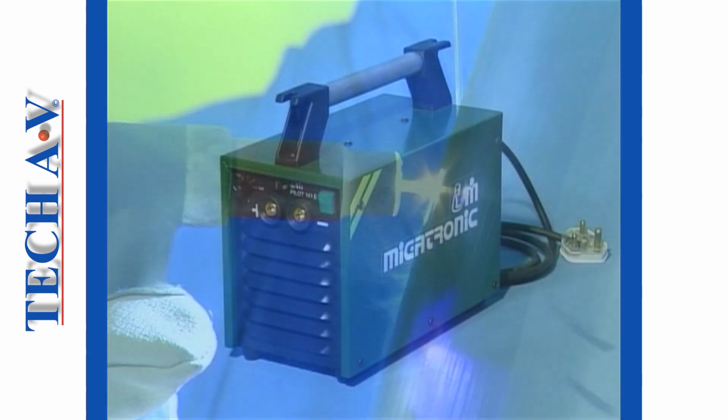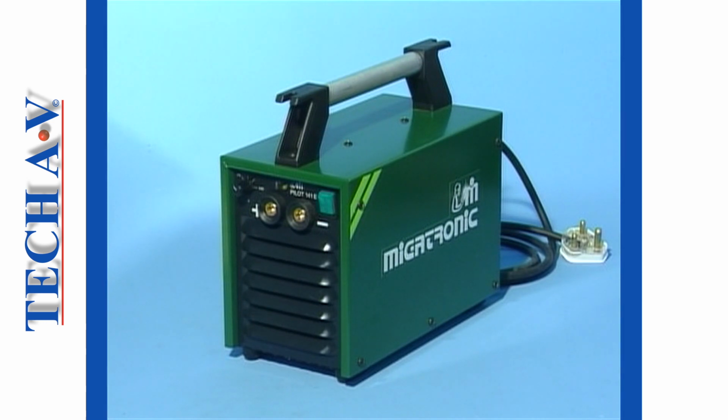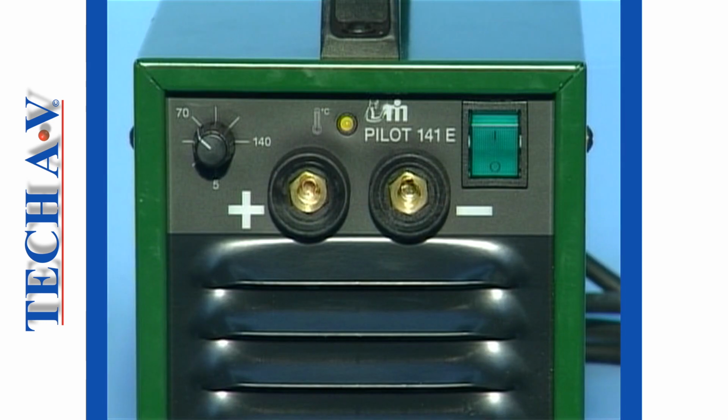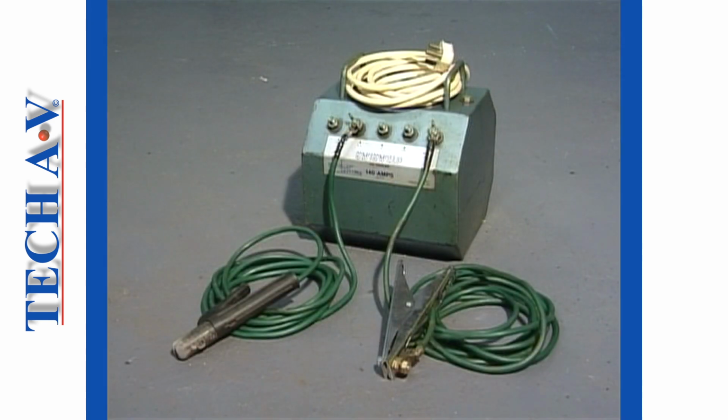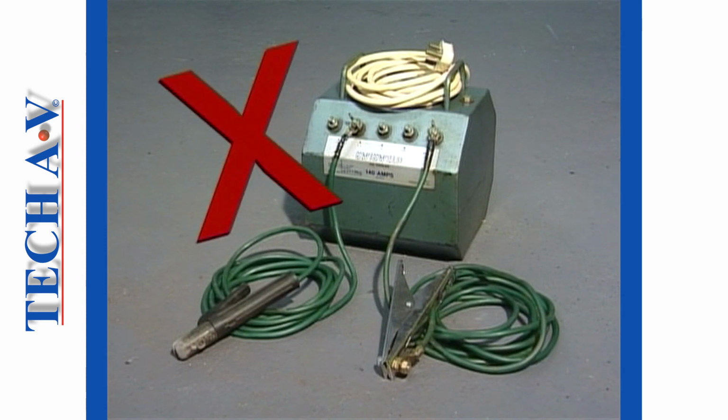The minimum requirement for a TIG operation is a machine that delivers a controllable DC output. Most ferrous metals are welded using DC. It must be noted that your average home use transformer is totally unsuitable for use with TIG welding processes.